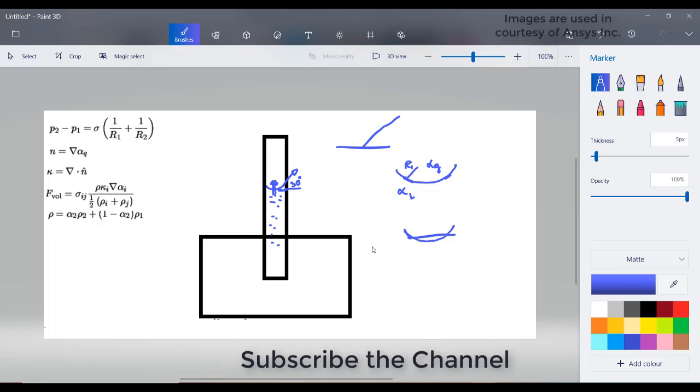The entire water column moves until it is balanced by the weight in the downward direction, right? That force term is added as a source term to the Navier-Stokes equation, the momentum equation that we generally solve in CFD.